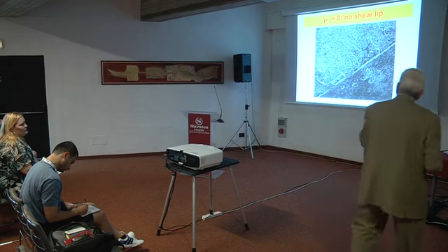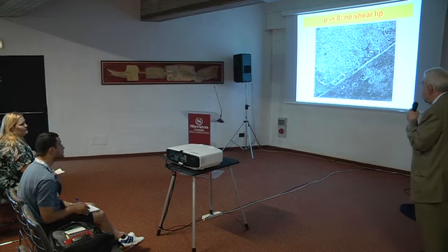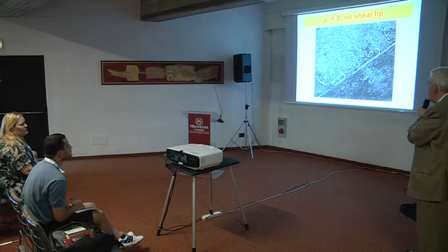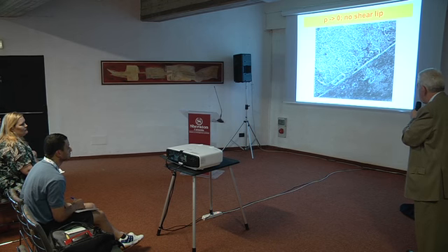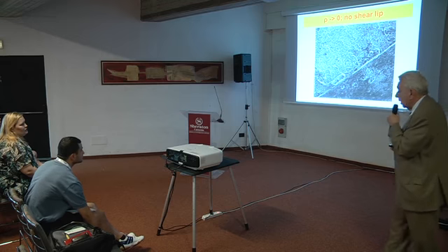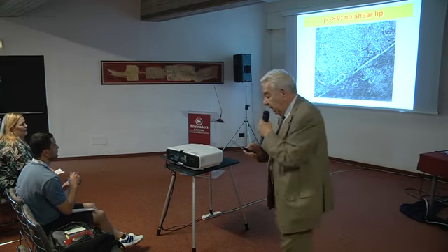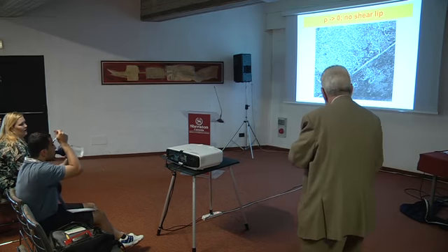So when the notch root radius is almost nil, there is no shear lip. You have just a tiny series of micro cracks that dot the surface.